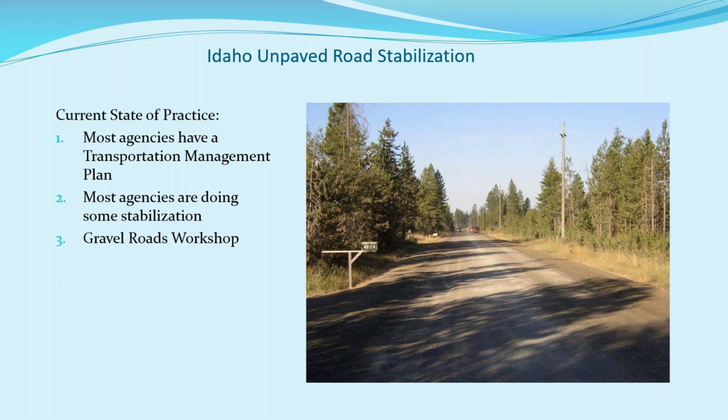It's a material they just come in and load it up into the truck out of the bank and take it out onto the roadway, and that's pretty much what they dump out on the roadway. The only problem is you don't know what your gradation is. You don't know how much binder you have in it, and it changes depending upon what part of the pit you're getting it out of.